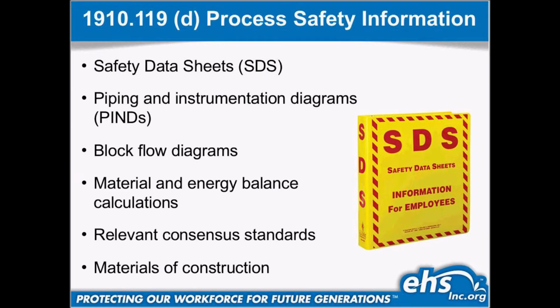There's a lot of stuff out there that is free for the taking. You can go directly to the NIOSH website and download the PDF of the NIOSH Pocket Guide. You can also download different programs that will have enough information, like WISER, W-I-S-E-R, which is the Wireless Information System for Emergency Responders. You can also use CAMEO Chemicals, either on your phone apps or your computers. It will give you a little bit more information. It will complement what you learn from the SDSs. And like I said, SDSs are supposed to be chemical specific, but they're not the ultimate document. You need to do a little more than that.